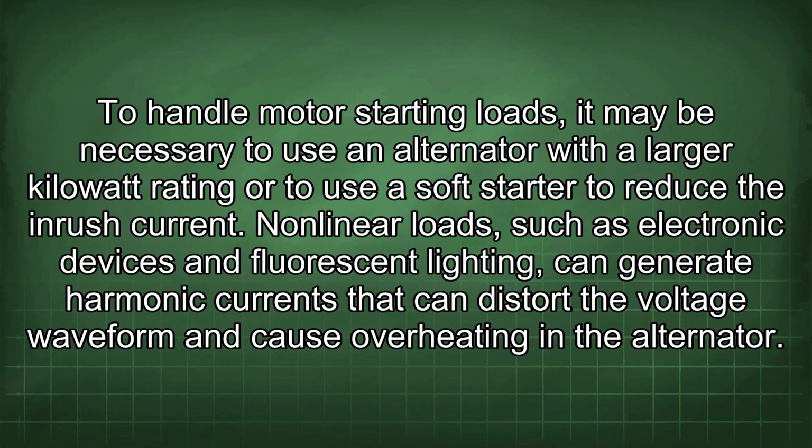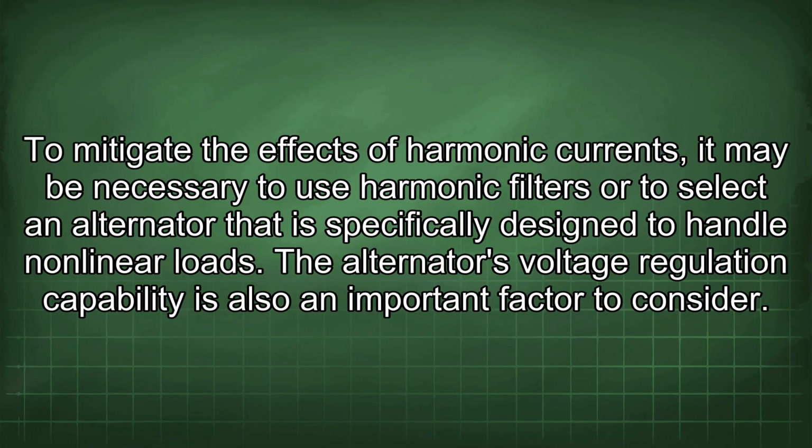Nonlinear loads, such as electronic devices and fluorescent lighting, can generate harmonic currents that can distort the voltage waveform and cause overheating in the alternator. To mitigate the effects of harmonic currents, it may be necessary to use harmonic filters or to select an alternator that is specifically designed to handle nonlinear loads.